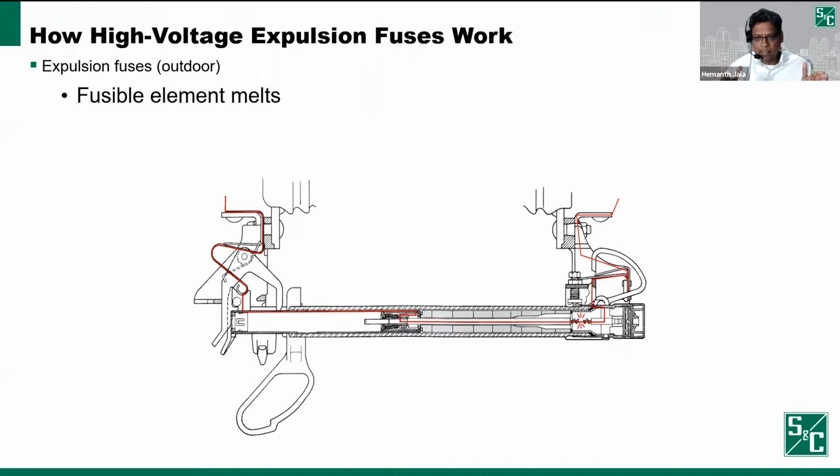This is a 90-degree rotated fuse unit. In real life, this fuse is actually 90 degrees rotated. I just put it in a horizontal position so that you can see clearly. This is a fuse in a mounting. So that's the top, and this is the bottom of the mounting. You've got the cables coming from here, and you connect here, and then the load is connected to the terminal pad that's up here.